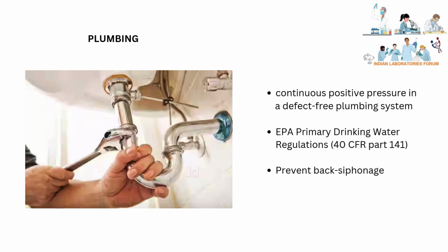Backsiphonage occurs when there is a drop in water supply pressure, causing water to flow backward into the water supply system or other plumbing connections within a facility. This can happen when a fire hydrant is opened or during a water main break, among other situations.